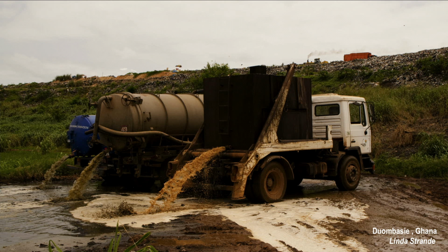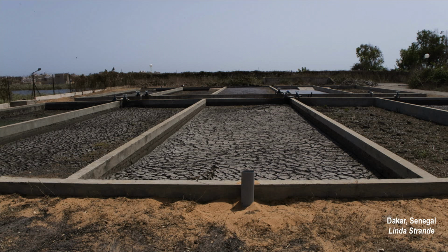Fecal sludge must be removed constantly from many household-level technologies, and yet there are few treatment processes available that are able to treat it. Here is a great example of a sludge drying bed. The sludge trucks from the previous slide would come here, dump their sludge onto one of these dedicated drying beds. The beds are made from layers of gravel and sand. The sludge layer is applied on top, and the solids stay on the sand layer and dry out under the sun while the effluent percolates through the sand and down through the gravel where it's collected. The effluent, don't forget, is another new product that must be treated in a separate process before it can be